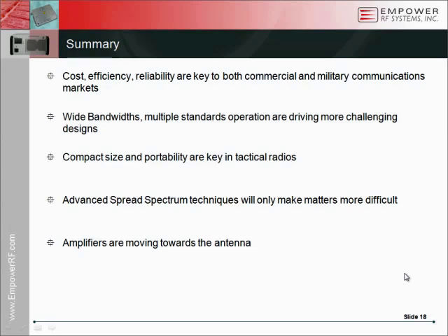I think, in my opinion, three-way Doherty is more applicable where you have larger peak-to-average ratios. If you're talking about greater than 8 or 9 or 10, three-way Doherty helps you more. If you're talking about more back-off and keeping your efficiency, I think the circuit will be more sensitive than two-way Doherty.